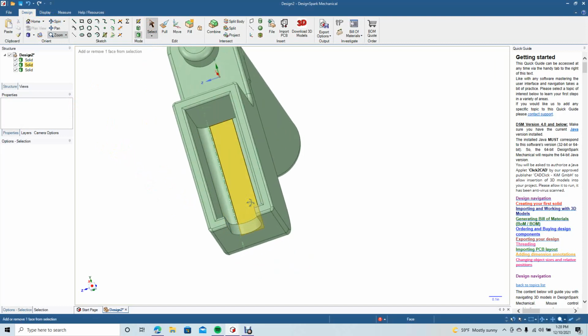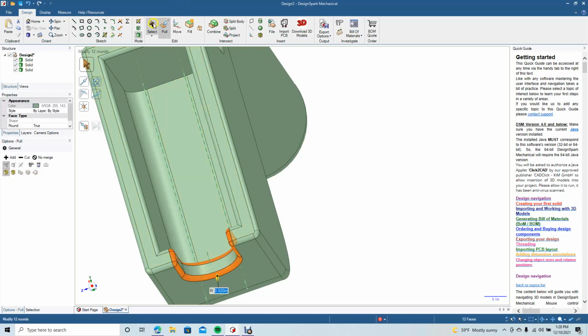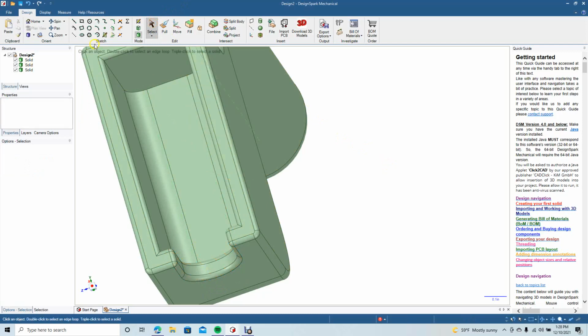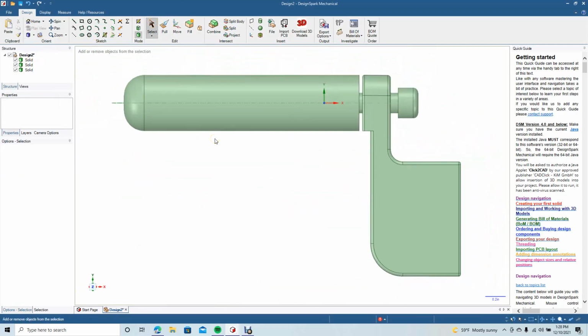Let's zoom in, Control plus. I'm going to put a fillet around these. So click until everything is selected. Click and drag. 0.2. We'll click off of it. We'll go over here to the top view. Okay, that's going to end the tutorial.